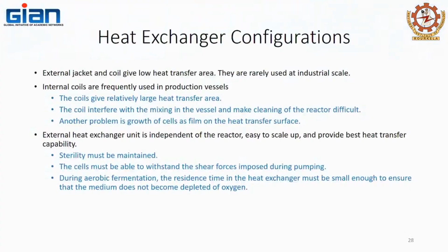Another problem is the growth of cells as a film on the heat transfer surfaces. Again, fouling. Those biofilms get generated on the heat transfer surfaces, so you have to make sure that you clean them to maintain an appropriate heat transfer level.